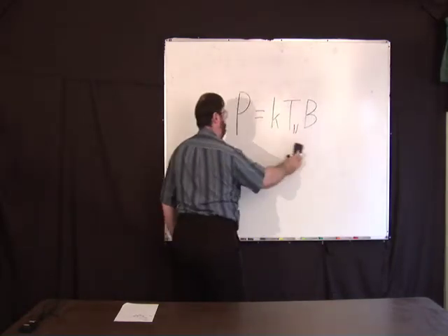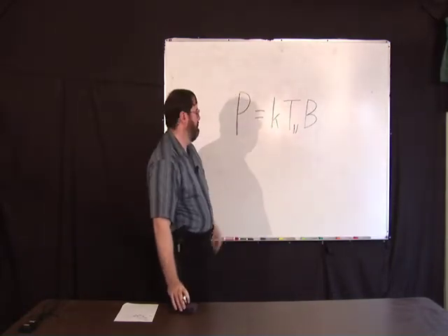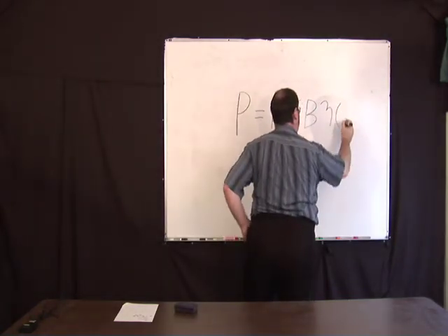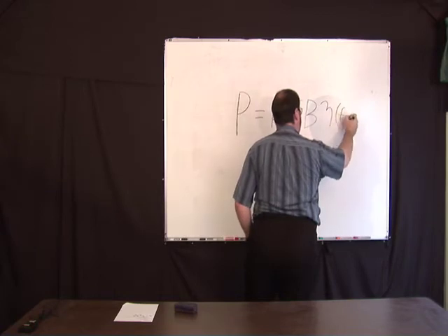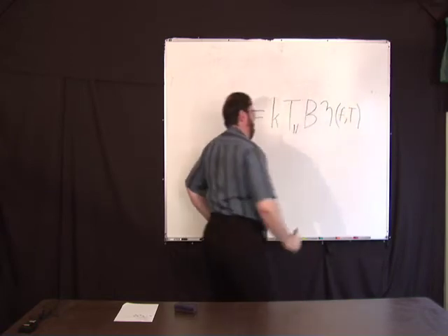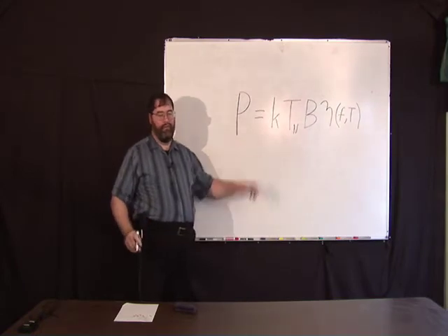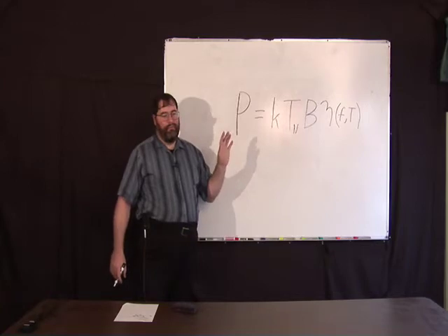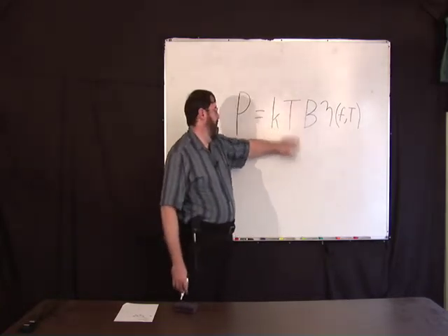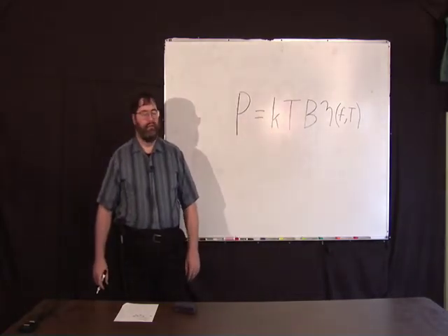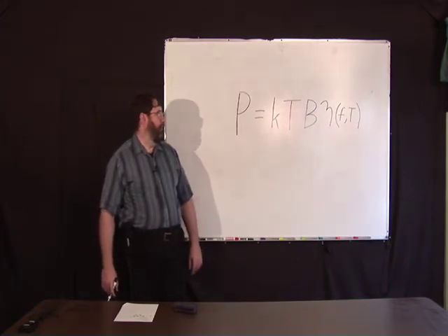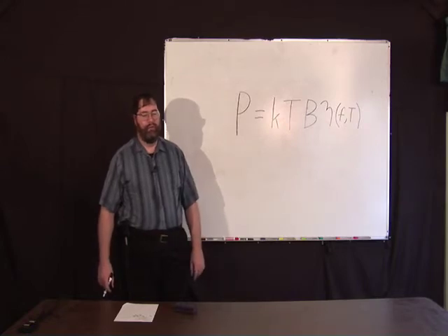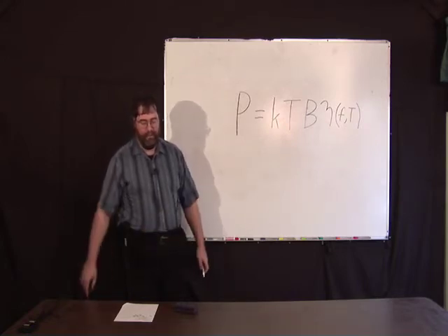there is a correction that can be made to this expression. You just add a term, usually denoted by eta. This is a function of frequency and temperature that keeps this thing from blowing up over an infinite bandwidth. Of course, this wouldn't now be the noise temperature, it would be the physical temperature measured in Kelvin. For precision measurements, you do have to include that term in your analysis. We're not going to say much more about that in this episode.